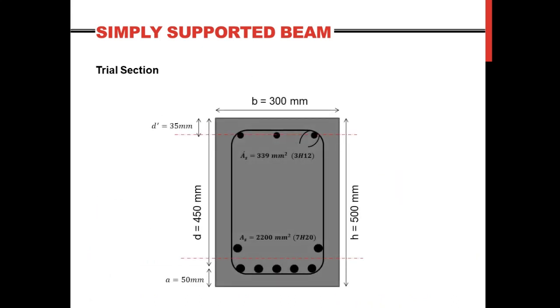Now I can tell that we have successfully assigned the area of reinforcement required for our cross section, and by doing so I think we are done with the bending design. These are the rebars that we need to counter the applied bending moment. Just remember, we haven't yet designed the shear links, and hopefully we're going to talk more about this in the next part.